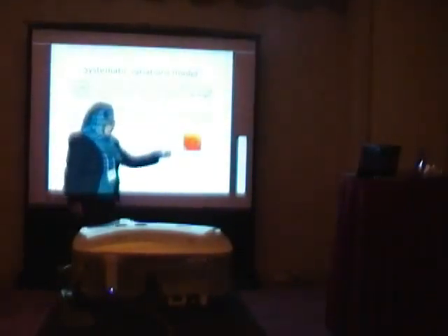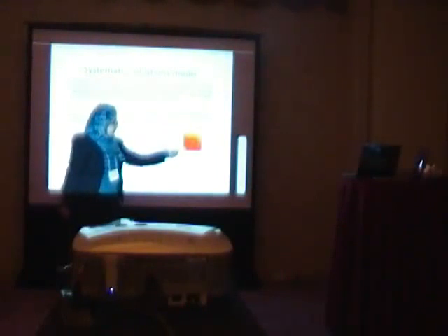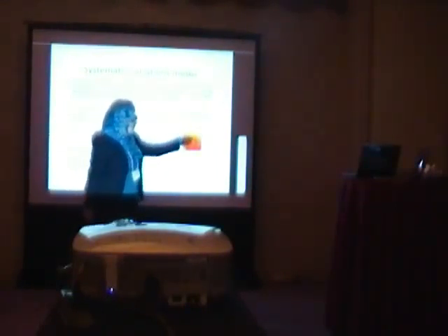So for this threshold, for example, we have the original value for this threshold, and we know its standard deviation. We can calculate this threshold at this point, and this point, and this point, using the polar distance between the origin and each point. This way, we have a variation map for this section. Similarly, we get a variation map for gate length, a variation map for oxide thickness, and a variation map for line width.